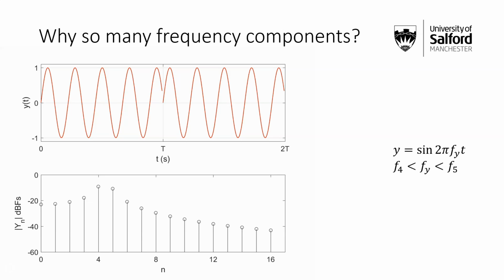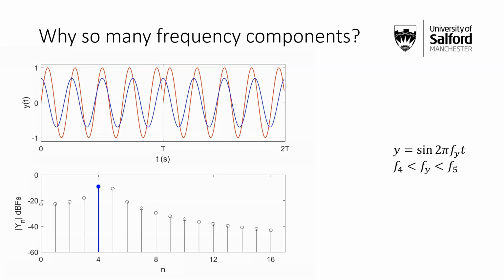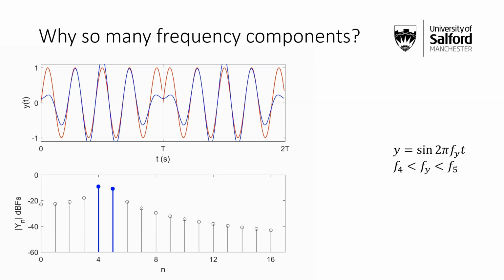But the frequency we've put in is between the 4th and 5th harmonic. So you can see immediately in the spectra at the bottom, those are hooked up the most, but the others are all doing something quite significant as well. And we're going to see 4 and 5 come in first, and then we'll go in order of decreasing significance. So let's put in 4 and 5. Even though those two don't match very well, we then start to add more and more, in order of reducing significance.